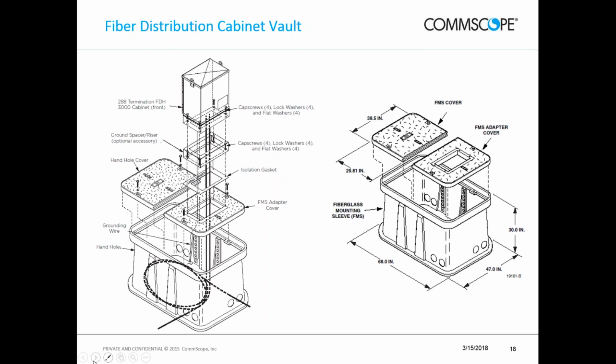Within this vault, this one is 47 by 68. So this is a rather large one, at least in my experience. Don't usually like to use them that big if we don't have to, because then that requires a backhoe to come out and dig the hole. With smaller vaults that are like 30 by 60, you can hand dig those. It's not fun, but you can hand dig them. It's not too tough of a task.